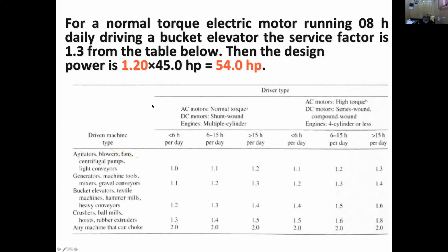So you can see here the table. Are you able to see this table? Yes, sir. We can see it. So this table will help you in finding the actual power for which the belt is to be designed. The actual power to be transferred is 45, but if you design for 45 horsepower only, then your design will not sustain at the operational state. So you have to apply the rating to this power, then you can get the actual power for which you will design the belt.